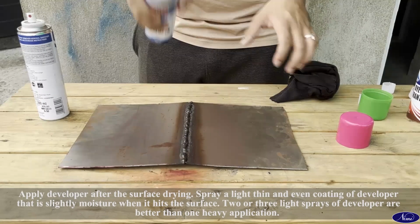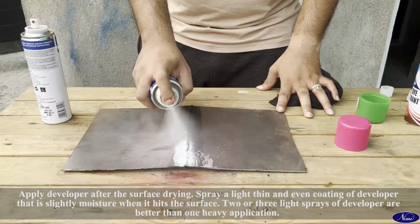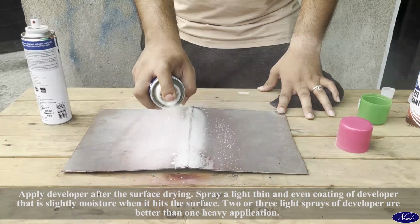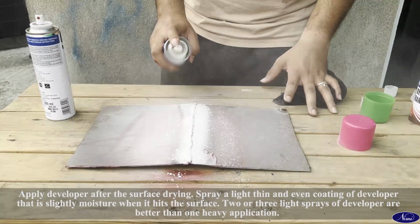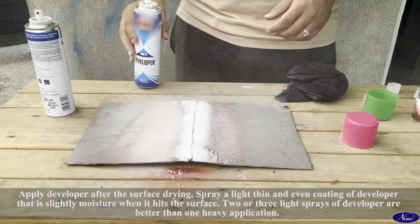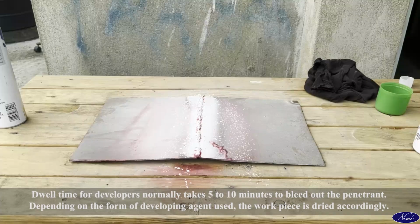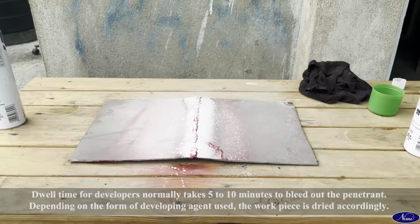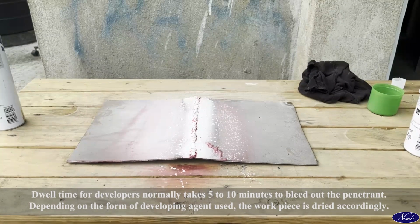Developer application. Apply developer after the surface drying. Spray a light, thin and even coating of developer that is slightly moist when it hits the surface. Two or three light sprays of developer are better than one heavy application. Dwell time for developers normally takes 5 to 10 minutes to bleed out the penetrant.